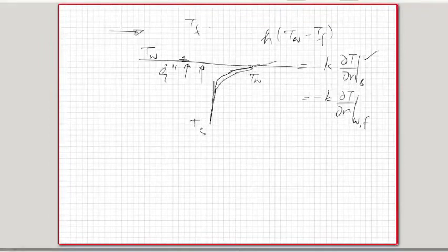If I measure on the fluid side, there will also again be a temperature variation. So finally it goes to Tf, and this is T wall. The difference between Ts and Tf is what is driving the overall flow, and at the surface, if I equate the heat coming from the interior of the solid to the one that is going out, then I can quantify it using this K del T by del N at the first layer. So it is K del T by del N at the wall in the fluid that would be equal to this.